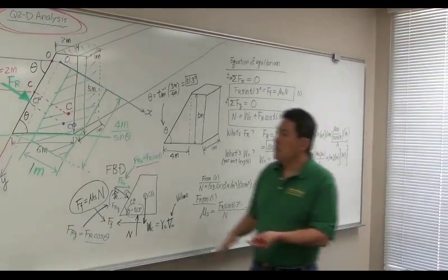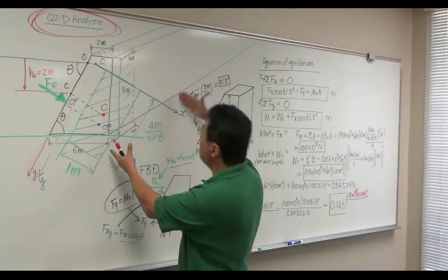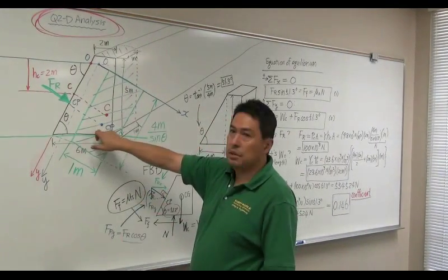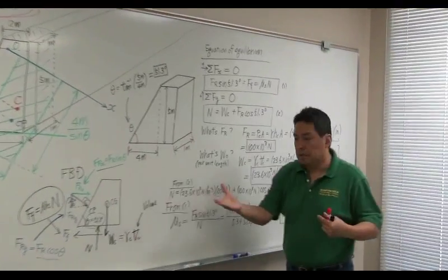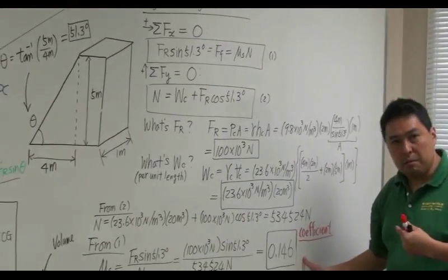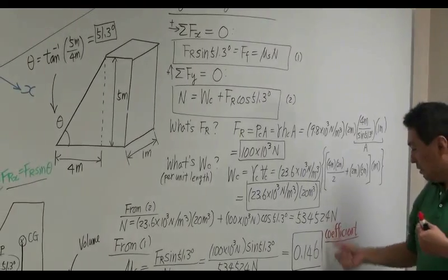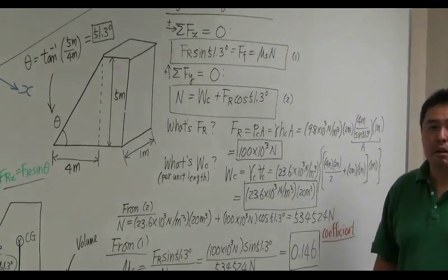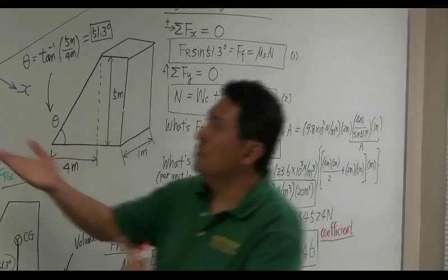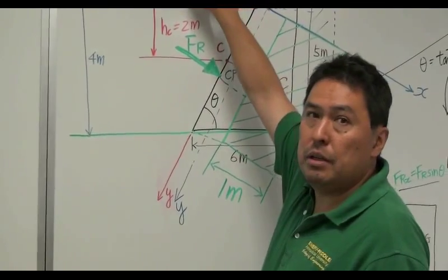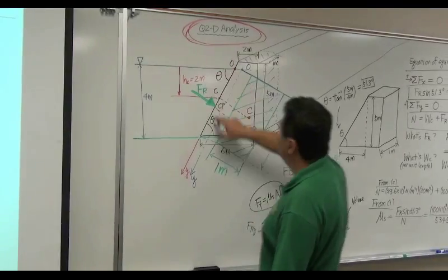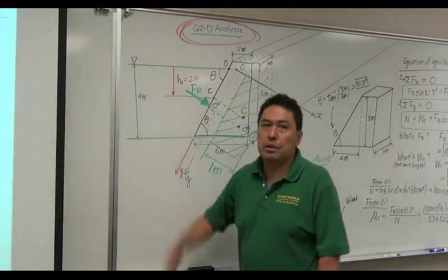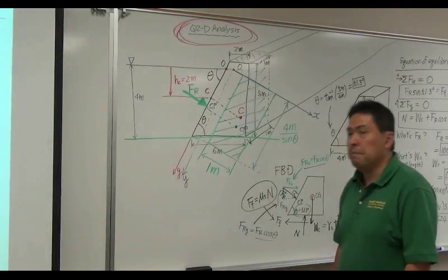Well, suppose you have a concrete block with 10 meter wide with this cross-section. How much static friction coefficient you need? Same, because it's coefficient. That's the beauty of using coefficient together with quasi-two-dimensional analysis. Okay, so you are going to use the 2D analysis to answer the 3D objects problem.